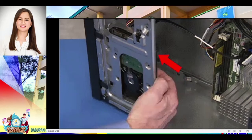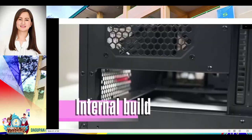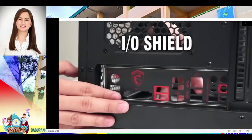To mount the drive, find a 3.5 drive bay to install the drive in. If you have trouble finding a place to mount the drive, consult your case documentation for suggestions. Slide the drive into place until the screw holes on the slide are lined up with the holes in the case. Then install the screw.